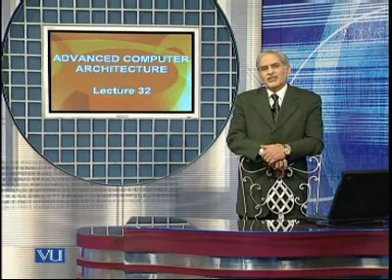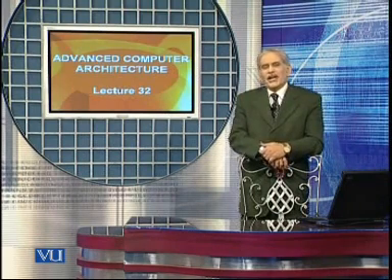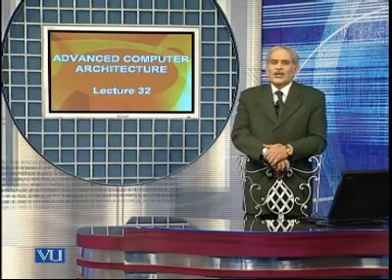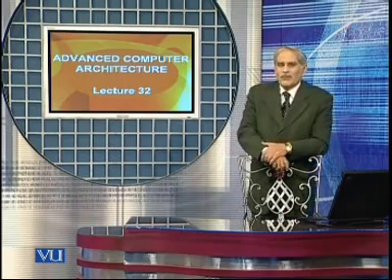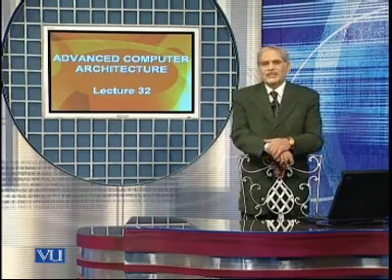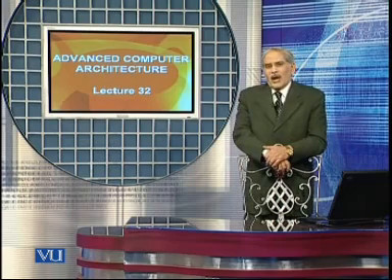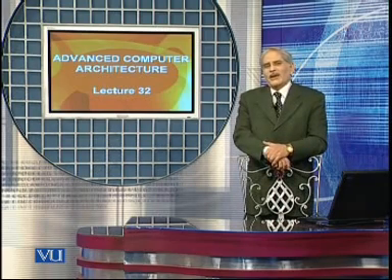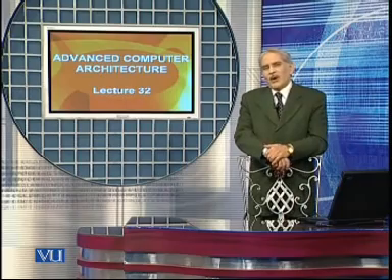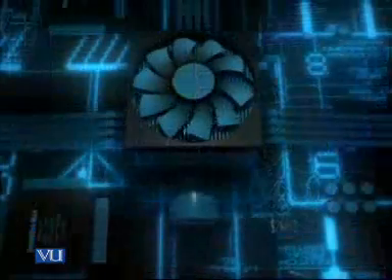The other demerit of wider memory design is that if the main memory is to be expanded by the user, it must be expanded or incremented as double or quadruple. That is the same as the memory width. This means that we have to place some larger chips in order to expand the memory, and we cannot work with smaller sized memory chips.